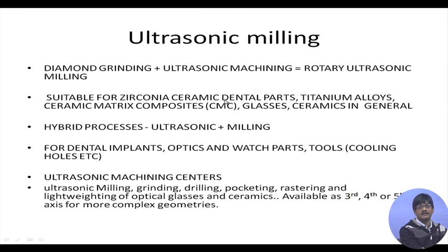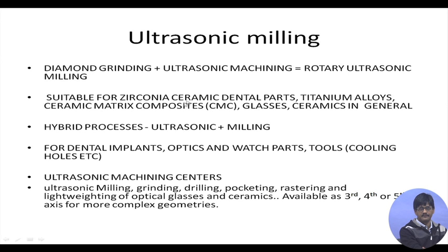That means these are dental part replacements, zirconia ceramic, that means zirconium oxide, titanium alloys, that means difficult to machine materials, ceramic matrix composites or CMC, glasses and ceramics in general. So, these are the areas in which rotary ultrasonic milling is resorted to.